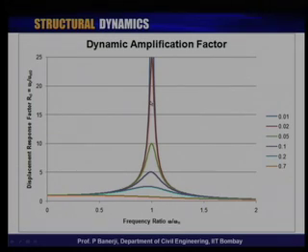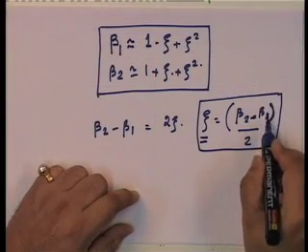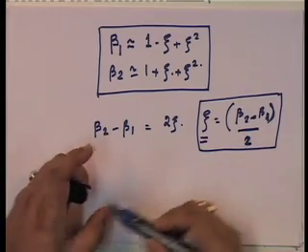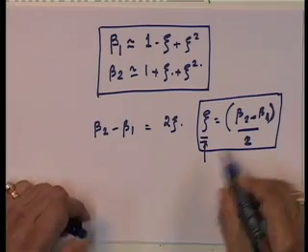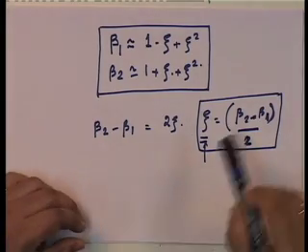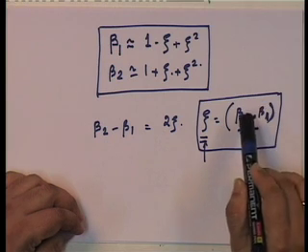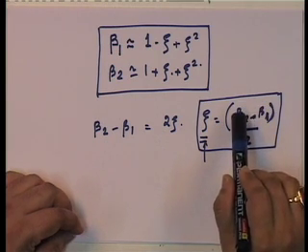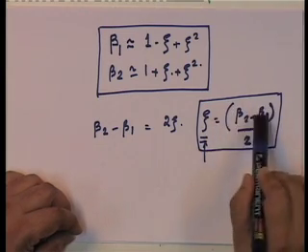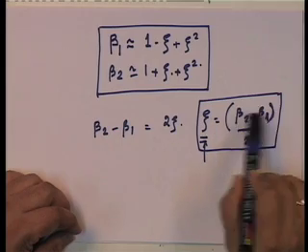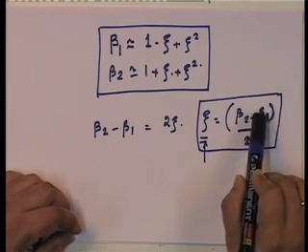In other words, the point that I am trying to make is that the estimation of xi from bandwidth becomes much more stable, and the error in xi from the half power bandwidth method is small. These are the frequencies at which the power becomes half, and the bandwidth, which is beta 2 minus beta 1, gives you the bandwidth.